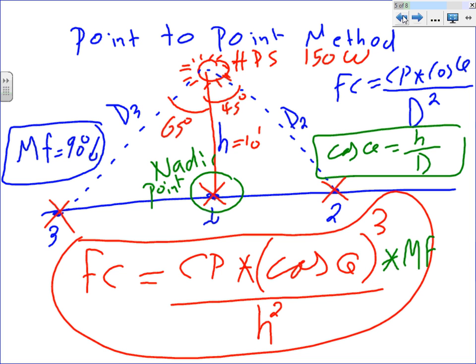Any question, guys, about this calculation? That's basically it. As I said, I might add other factors. If we put this fixture in a room and there are walls and geometry around it, which is coming, then you add the coefficient of utilization based on the geometry. And if you have a guard on it, you add another derating factor. If you don't have them, then assume it's always 1, like a power factor.